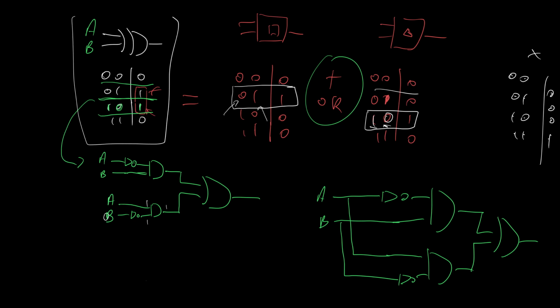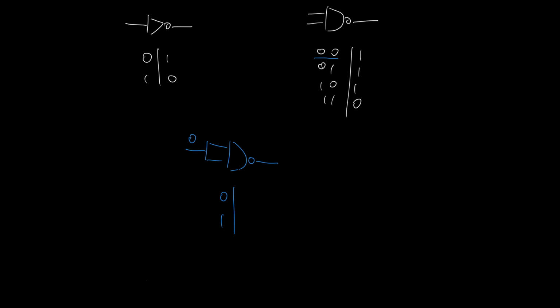There isn't really a clever way of deriving this, or maybe there is, but it doesn't really matter. All we need to do is observe that if both inputs of my NAND gate are the same, then when I come to compute the truth table here, if 0 comes in, then 0, 0 on the input gives me a 1 at the output.